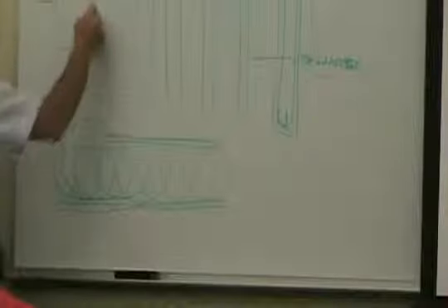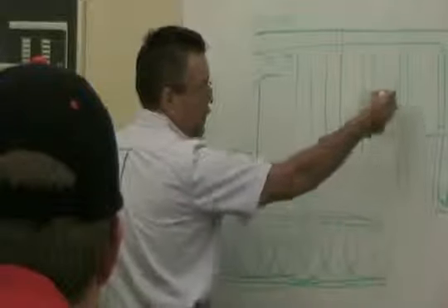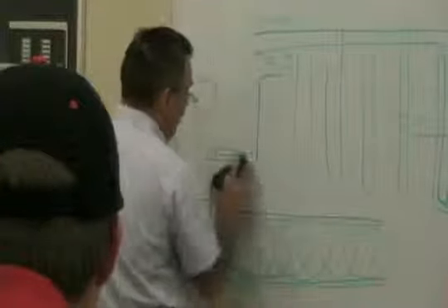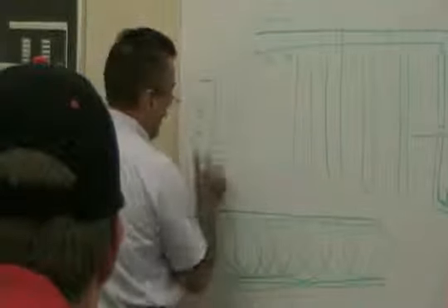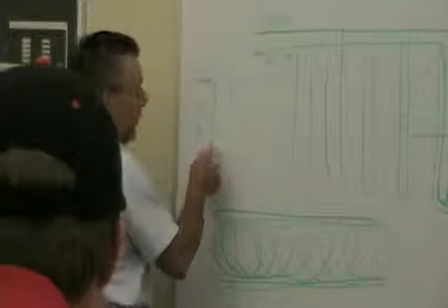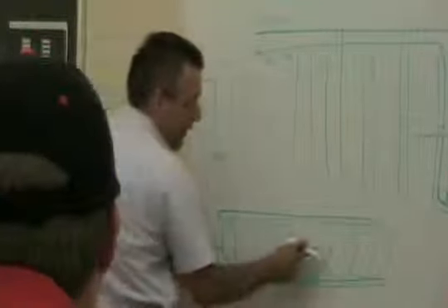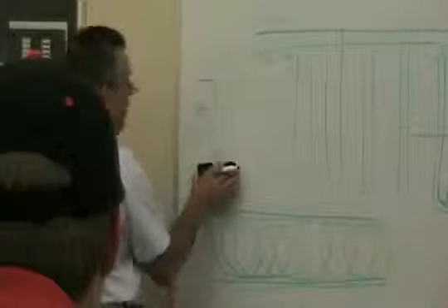I've got a ditch that's generally 5 foot deep to 7 foot deep, and this slinky is laying in that ditch. This is a vertical well application as well as a horizontal well application. I can dig the same ditch and put my supply and return pipe in it in a horizontal application. Generally, your piping lengths might be 60% more in a horizontal application because you're not getting quite the conductivity as in a vertical well. This can be in a horizontal ditch. It can be laid in the bottom of a pond.